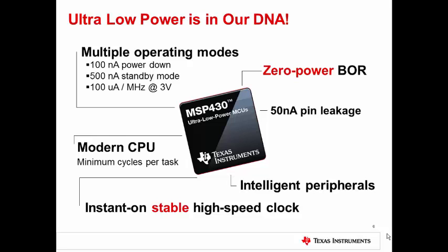A rich set of intelligent peripherals which can be used in different low power modes, including UARTs, which can wake up the device on reception, timers which keep counting in LPM3, ADCs which perform accurate conversions faster and efficiently, etc. A high-speed clock which is available instantly after waking up, among many other features.